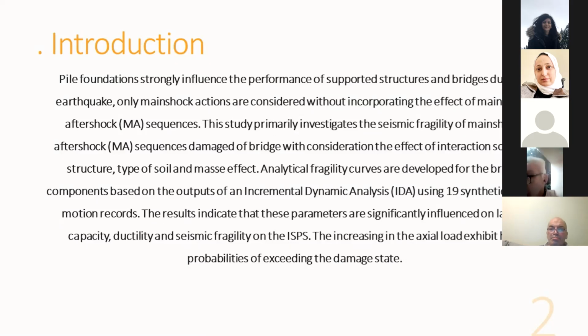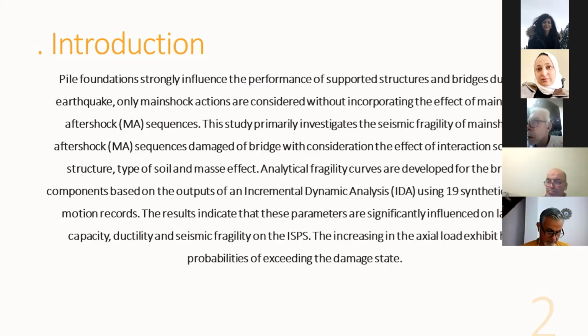Analytical fragility curves are developed for the bridge components based on the outputs of an incremental dynamic analysis, IDA, using 19 synthetic ground motion records. The results indicate that these parameters significantly influence the lateral capacity, ductility and seismic fragility of the ISPS. Increasing the axial load exhibits higher probabilities of exceeding the damage state.